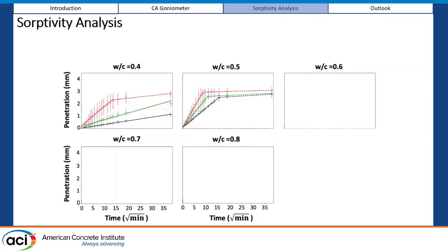So similar to carbonation depth, where we split the sample and spray phenolphthalein, we have to test it on a fresh concrete sample. Or at lab scale, we can put it under a desiccator, or in an area where we make sure it's not carbonated.